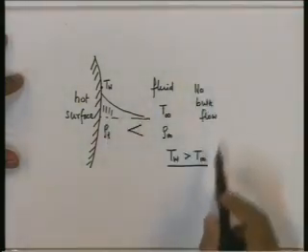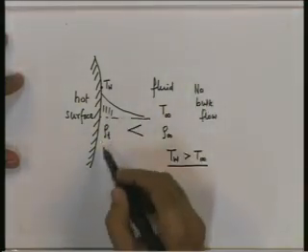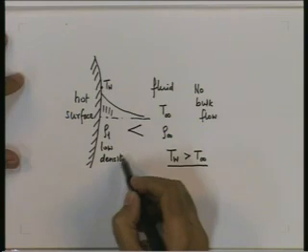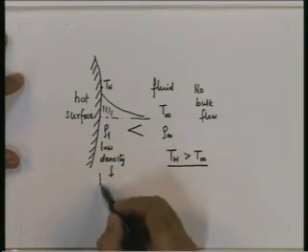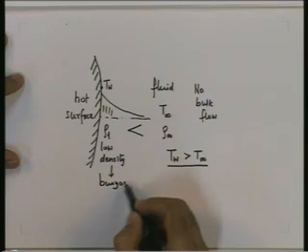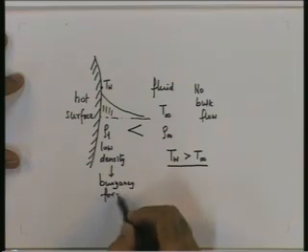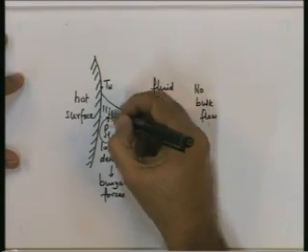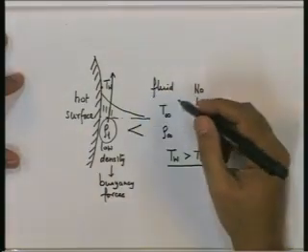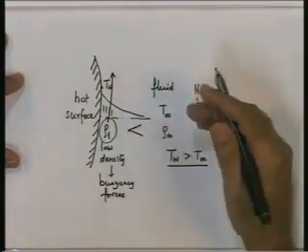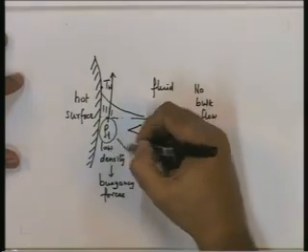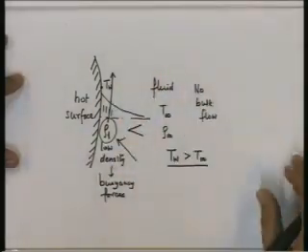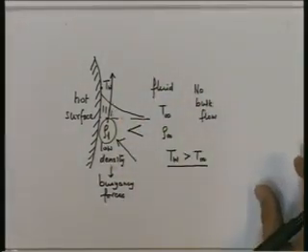So, that means in this bulk fluid there is a zone of low density. This zone of low density leads to buoyancy forces acting on it, and hence this zone of low density tends to move up, thus setting up the process of natural convection. It moves up, is replaced by fluid from the bulk, and the process establishes itself as a process of natural convection.